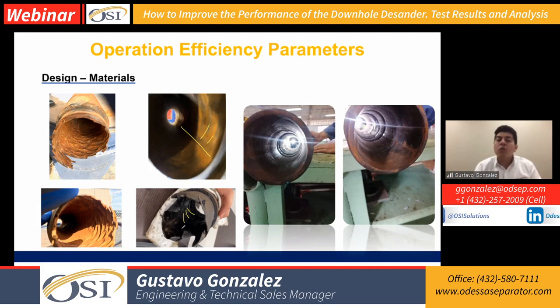And as we mentioned before, we always want that centrifugal force being generated in the sleeve. This other photo shows a well that was producing around 350 barrels per day. We got a runtime of almost 2.5 years, so it was a rod pump. But one of the things that you can see, because there were two different ranges on the production of the well, is that when they did that conversion from ESP to rod pump, they got a higher rate passing through the desanders. So we normally see around 400, 450 barrels per day.